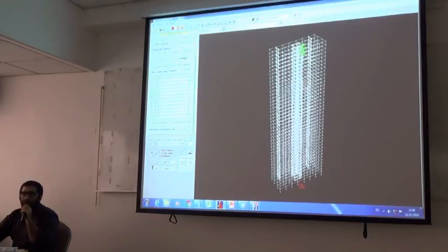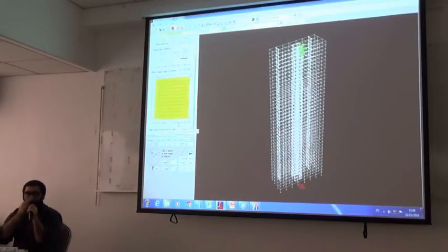And after we have selected the multiple tab, all we need to do now is select all drifts. You can select them one by one, but the easier option is just to press the select all button, right? It depends upon you whether you want to extract the histories of the drift results, or extract only the maximum and minimum results. But just for the purpose of demonstration, I will extract the history results for drifts so that you can see what is the amount of data that we get for drift history.